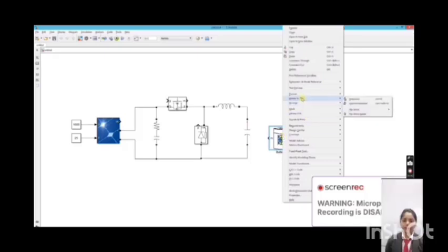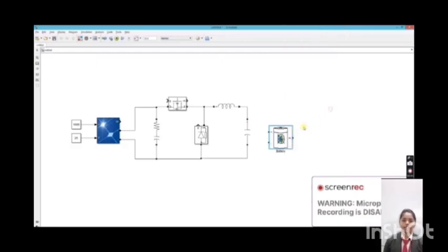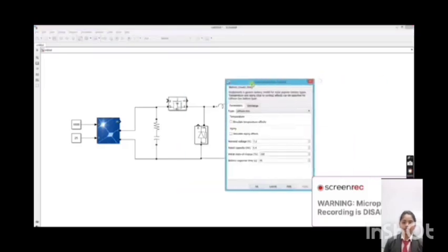The MPPT uses a perturb and observe algorithm. It works by slightly perturbing the voltage or current and observing the change in power. If the power increases, continue in that direction until it reaches the maximum power point. This ensures that the system operates at the optimal point of maximum energy extracted from the solar